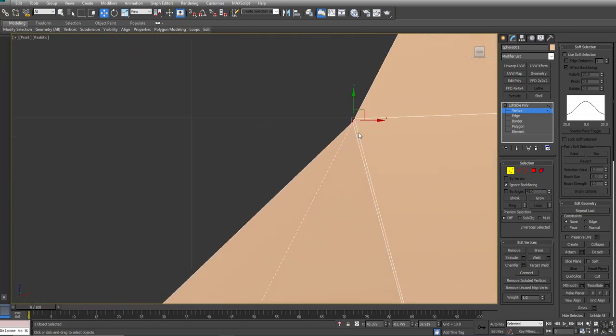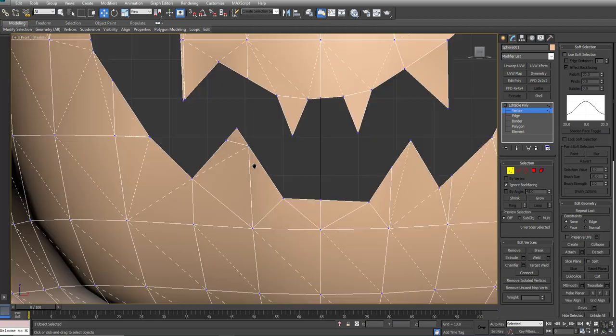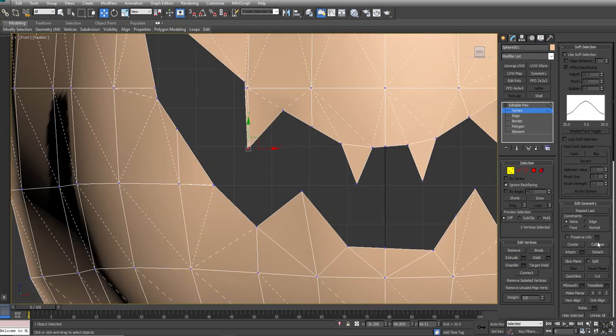I could tell looking at that guy that it looked a little weird to me, and yeah, there's 2 edges right there. And there's 3 here. I'm just going to select this one and delete them. Alright. I could probably collapse that down, grab this guy and delete him. Collapse this guy down. Ooh, that's a nasty little mess. Let's collapse that down.